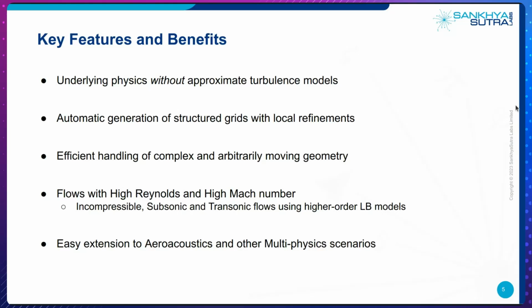And in terms of the workflow, CFD is quite intensive in terms of the requirement of the mesh that you generate as well, right? So we have an automated mesh generation workflow which generates a structured grid with the possibility of having local refinements. And the process is so simple that it probably takes just a few clicks to be able to generate your mesh. You don't have to worry about inflation layers and boundary layer capturing, these kind of things.